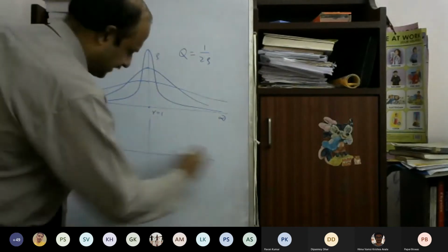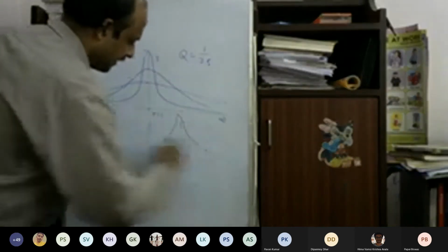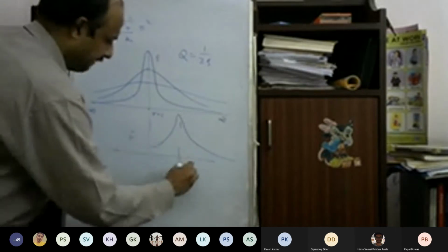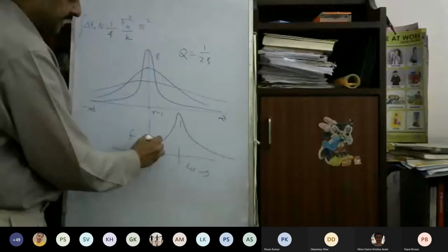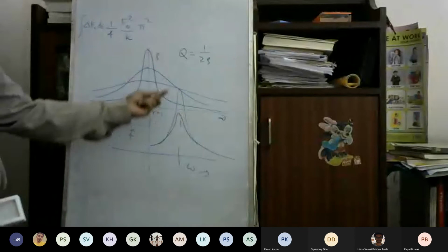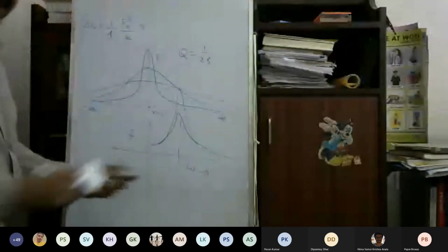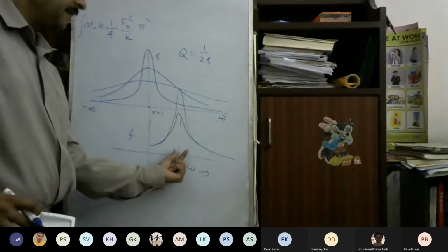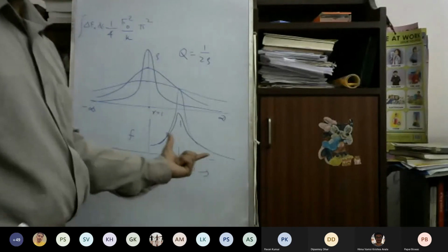and this is quite also clear from our physical intuition, because the frequency response function is like this, f is like that. So if damping is very small, then this becomes actually a large peak. So the energy dissipation, which is proportional to f square, actually becomes very small, just when you go a little away from the natural frequency.